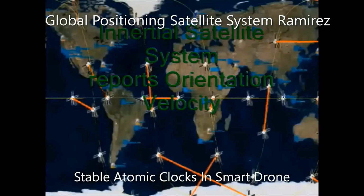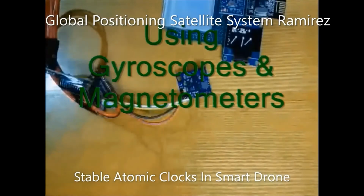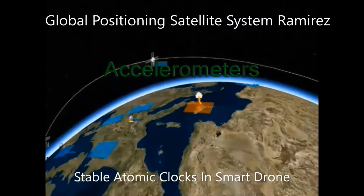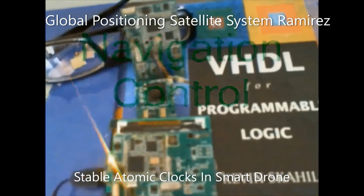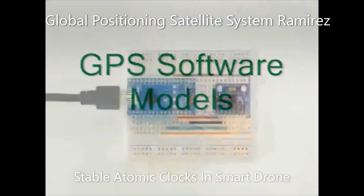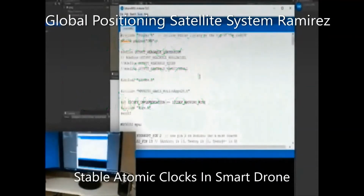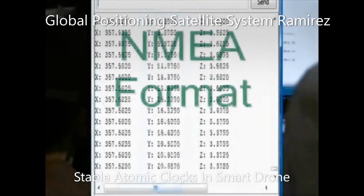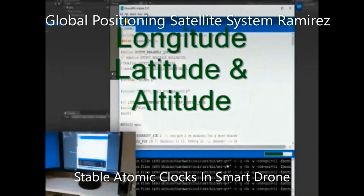The intelligent drone GPS receiver measures the time of transmission of 4 satellite signals from the time of arrival and time of transmission. The receiver forms 4 time of flight values which are equivalent to receiver satellite ranges. The drone receiver computes its 3-dimensional Cartesian coordinates and clock deviation from the 4 TOFs.